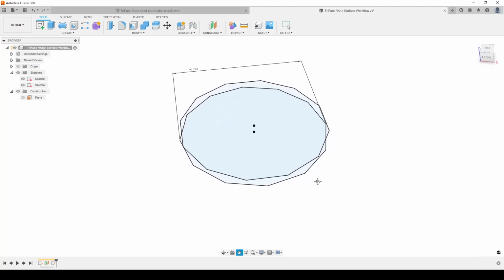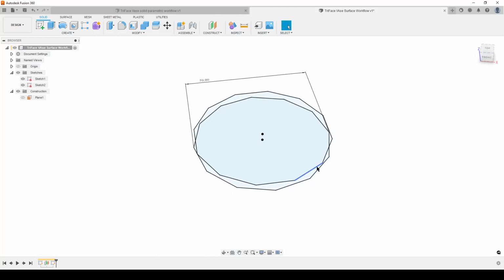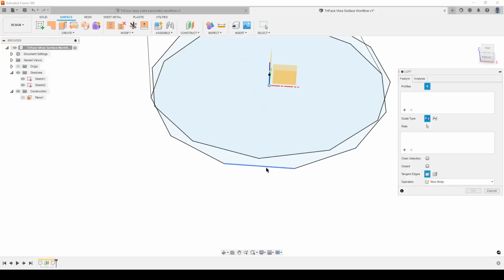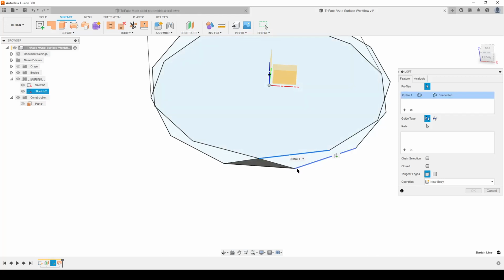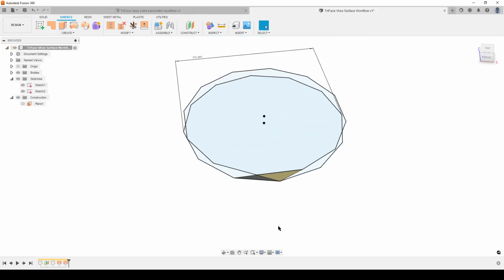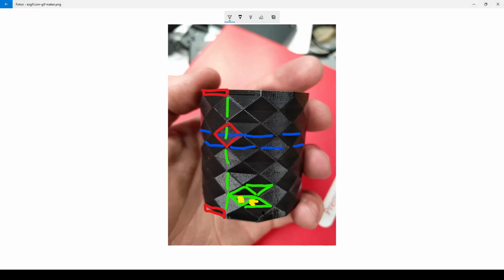That's just nice. So how do I now connect and make the triangular faces? To be honest, the first version I did, I used 3D sketching, but that's not really necessary here. We can use the surface tools and create surface lofts, because we can loft from a straight line to a point. Hit OK. We can create once again a loft from a straight edge to a point. Hit OK. And if we have a look now, we have made 2 triangles, this triangle and this triangle. Let's have a look at here. We have made one of these triangles and one of these triangles.